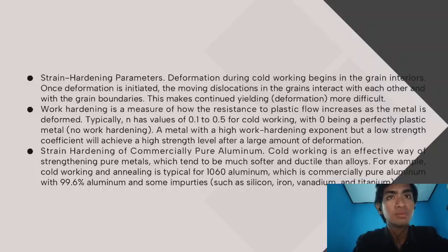The strain hardening exponent, or N, is the slope of the stress strain curve after the tensile yield strength. It exists for steel. K increases with carbon content, while N generally decreases. Both copper and brass have a much higher work hardening exponent than steel. Both K and N are affected not only by chemistry but also by prior history and the microstructure.